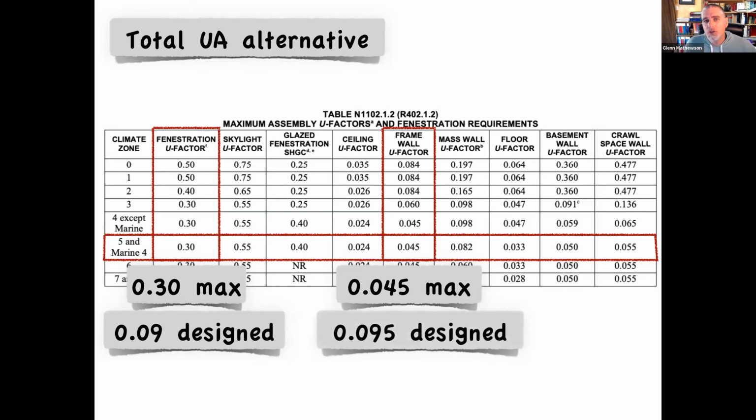So what this allows us to do is say, all right, I've enhanced the resistance to heat movement, or I've limited the allowance of heat movement in this one part of this meal, right? This one part of this house, the better window. And since I've made that part better, I can make another part slightly worse, right?